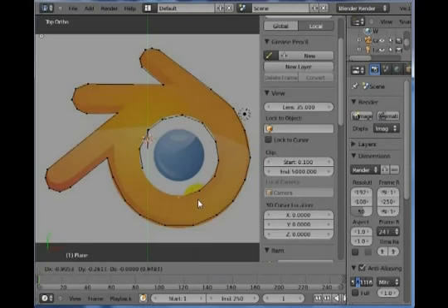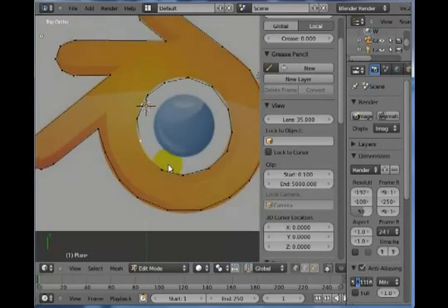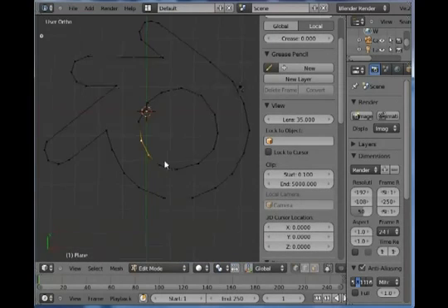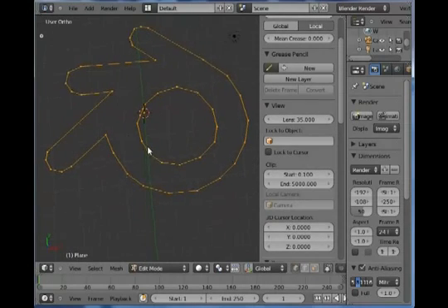Again, I get close to the end, so leave that space, select both of the end vertices, and hit F to face and fill it. Alright, so right now, do I have a shape? Well, if I start to spin it, nope. If I hit A for all and select all vertices, you see what I have so far. If I hit F12 to render, I know the camera would be looking at some of it. I don't see anything. Okay, that's because it hasn't been faced yet.